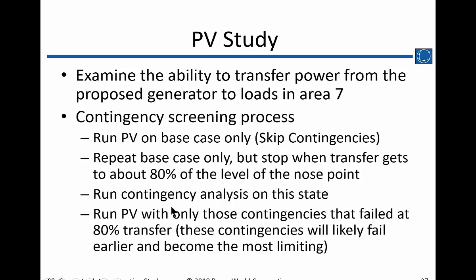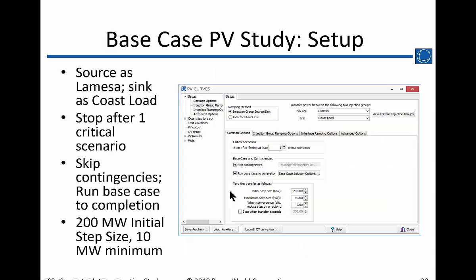If it's not, you could play with these parameters too. If you end up getting too many contingencies that fail or none that fail, then perhaps you can adjust the parameters, or if nothing fails, you could still maybe identify the ones with really low voltages or high changes in DVDQ multiples or whatever. But these are the parameters that we'll use to initially check it.